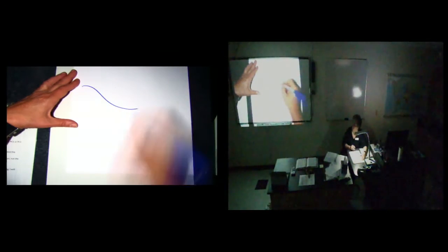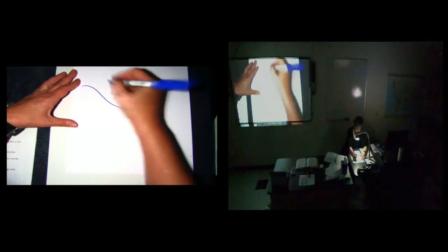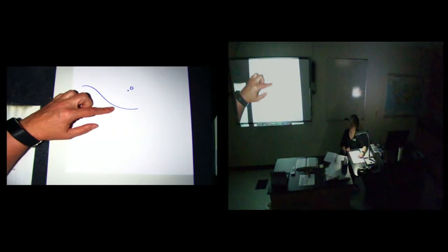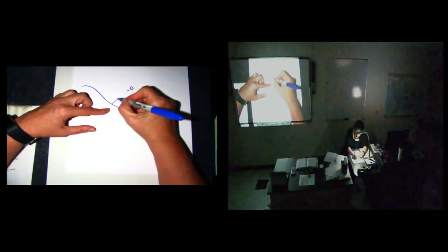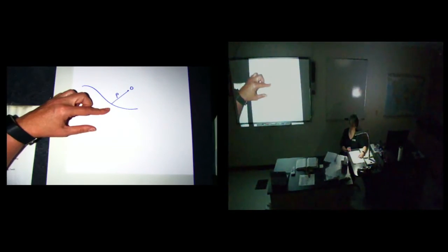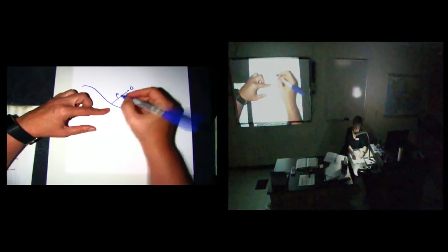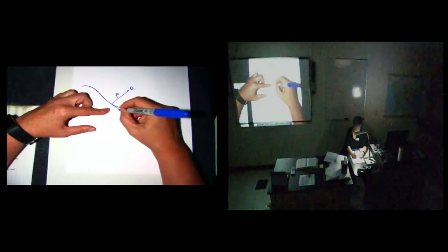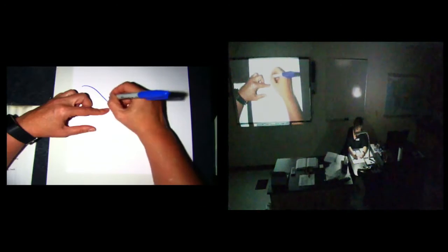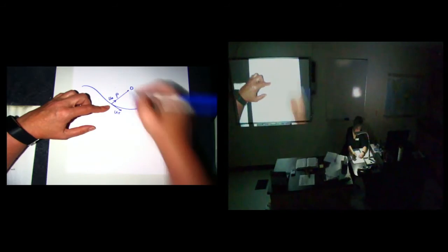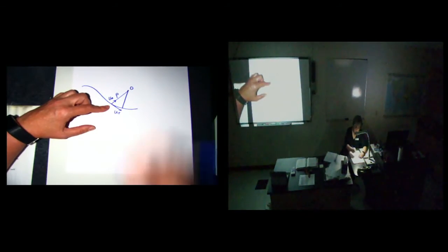Now at some point along my curve, and I've drawn it bigger than what I would normally think of from a calculus point of view, I've got a new rho, and now I have a change in angle. So this is a change in angle, or a little incremental angle. I have this increment right here, which is my ds. And now, if I look at it and kind of play with it, this is my normal vector. So my u tangential, dot tangential, ends up being my change in angle with respect to my normal vector, which is now an s divided by a rho times my normal vector. And this now is a v divided by my rho times my normal vector.